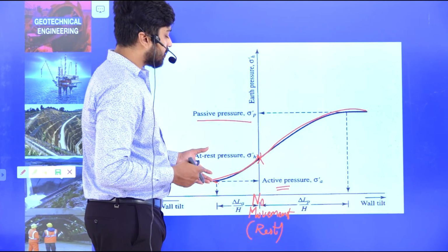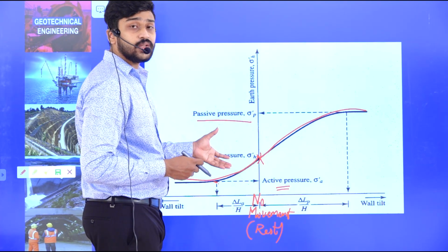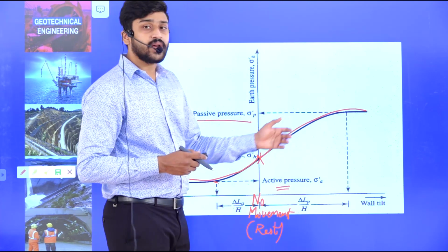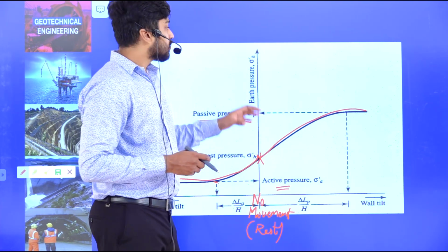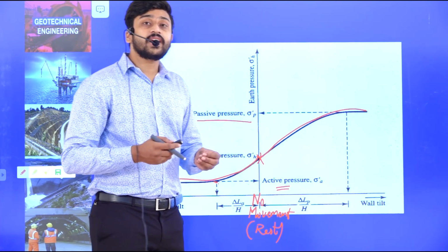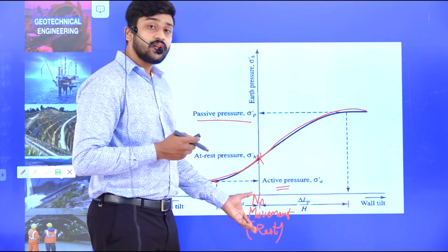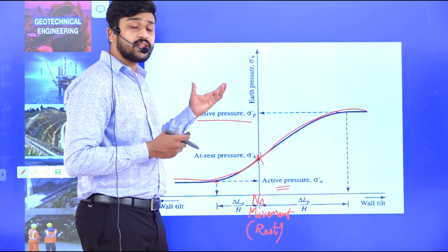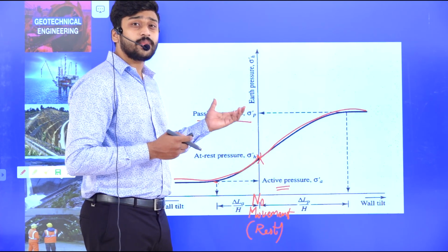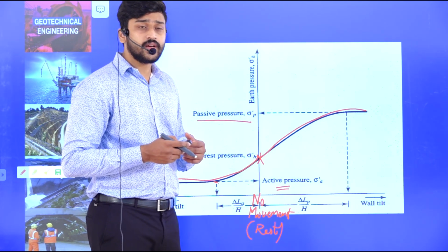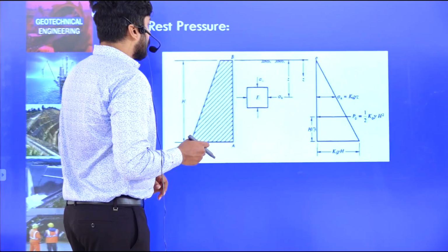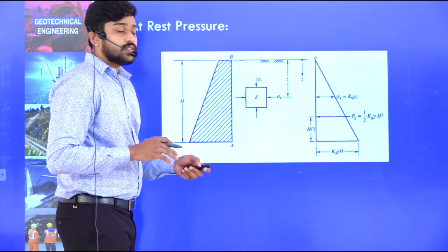So that is the difference here between active state, at rest state, and passive state. Based on this, we will try to evaluate the lateral pressure for the rest condition, and then the active pressure condition, and then the passive pressure condition.